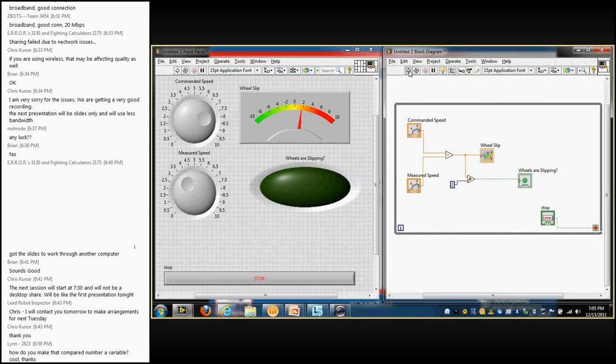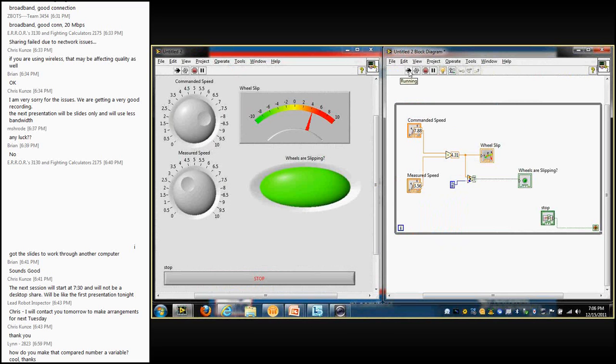You can visualize this really well with that highlight execution that I showed you earlier. If I hit run again here, you can see those numbers flow through the program. Then it'll loop back and run again now that we're in a while loop. If I move these, new values will arrive, and the math and the resulting program will change. Something to notice about highlight execution: it's not just visualizing it more slowly, it's actually running the program more slowly. So this isn't a way to debug in real time. It's quite a bit slower than the program would normally run.